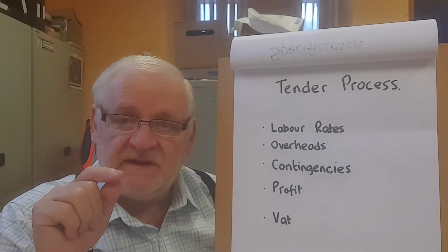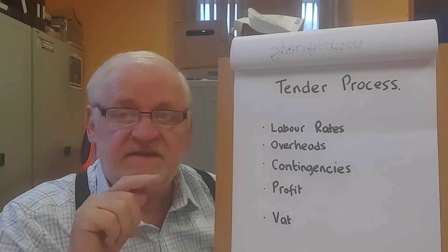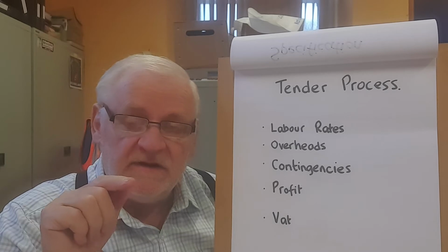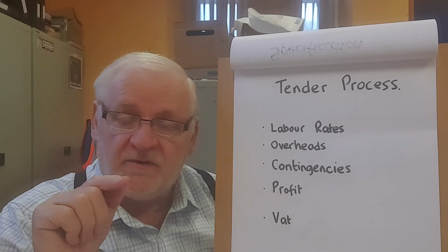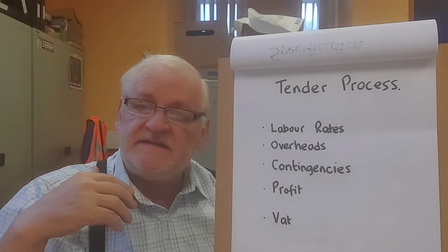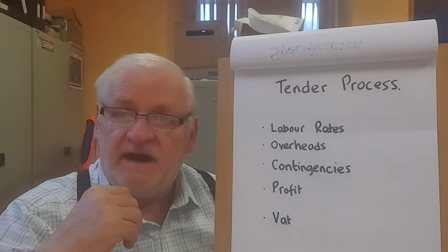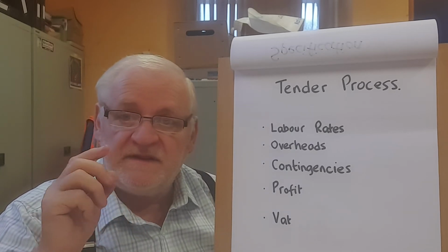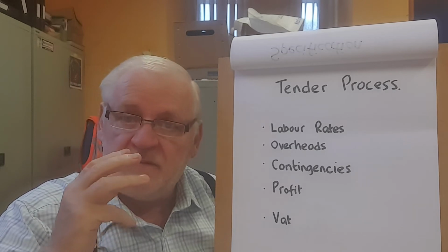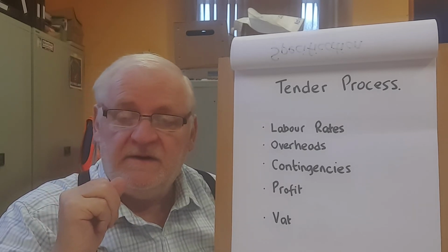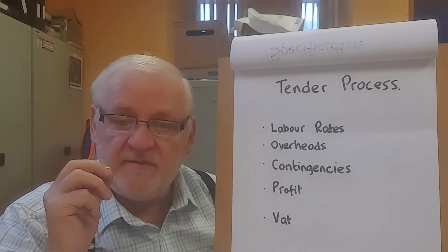But in that little book of mine, I talk about the different types of door. Is it a heavy door? Is it a very light door? Is it internal? Is it a fire door? Is it wide, extra wide, or is it quite a narrow door? Each of the doors take a certain amount of labor, a certain amount of time to enable you to hang them. And of course, it depends on whether there's 2 hinges or 3 hinges or 4 hinges. It depends on what type of lock is going to go on the door. All of these things affect the time and affect the labor rate.